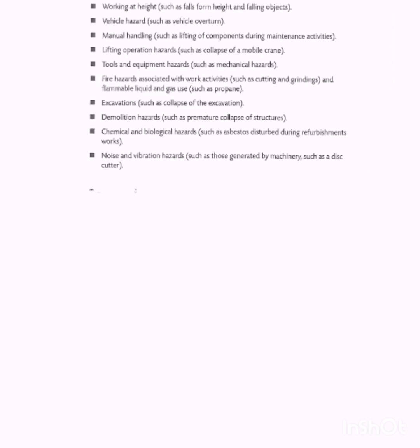And also flammable liquid like gas used, such as propane, right? That is a fire hazard. Then excavation, such as collapse of the excavation, right? Then demolition hazards, such as premature collapse of the structure, right? So you have to be careful when you are demolishing a building, right? Maybe if you are demolishing from under, maybe the strength of the basement is no longer good, so the building will also collapse on someone.